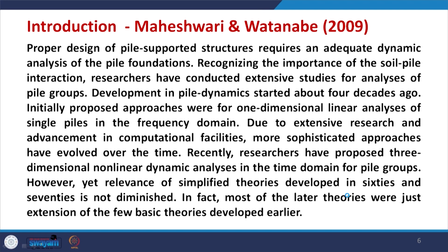Initially proposed approaches were for one dimensional linear analysis of single piles in the frequency domain. So, the first few papers were in the frequency domain, and later on it was extended to the time domain also. Due to extensive research and advancement in computation facilities, more sophisticated approaches have evolved over time. Recently, researchers have proposed 3-dimensional nonlinear dynamic analysis in the time domain for pile groups.